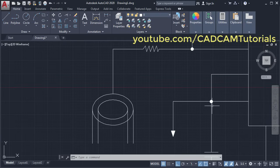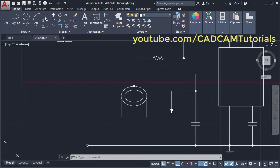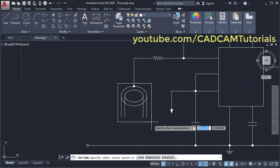Then we need this donut, we will copy it. Click on copy, select this donut, enter, then specify this center point as a base point, click, then click on this endpoint, enter. Then click on rectangle, then click first point here and second point here.